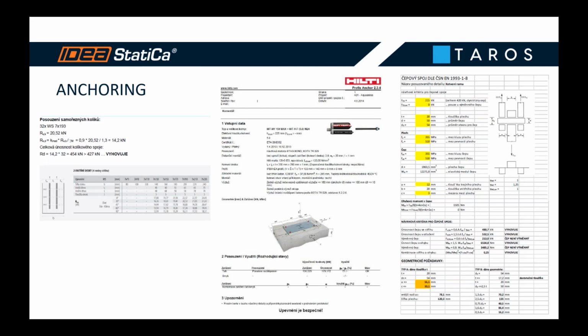In the middle, you can see the Hilti report from Hilti Profis. I used it to design anchors, and on the left, this is just a table to design self-drilling dowels, because this top part of anchoring is connected to the timber column using self-drilling dowels. And just get the force, find the resistance in the table, and get the result.